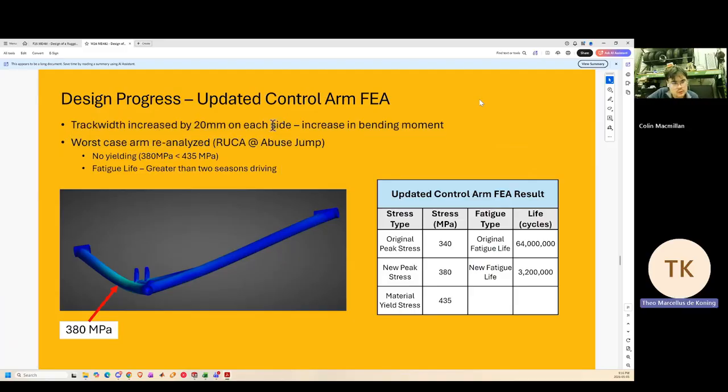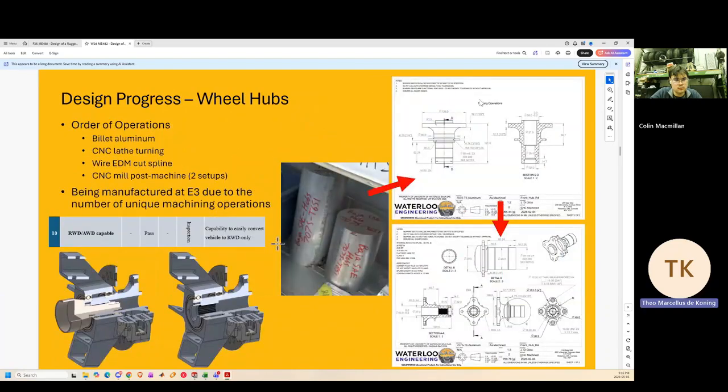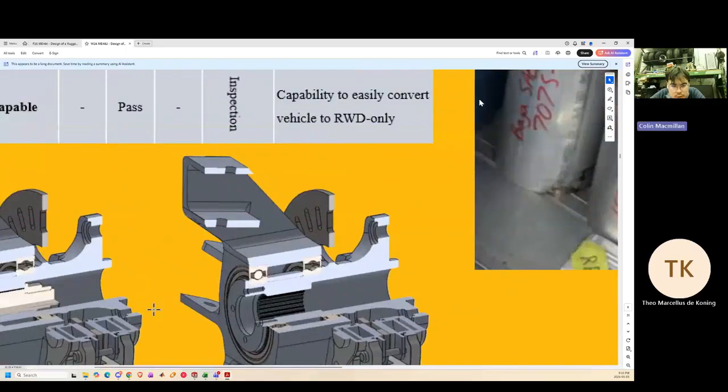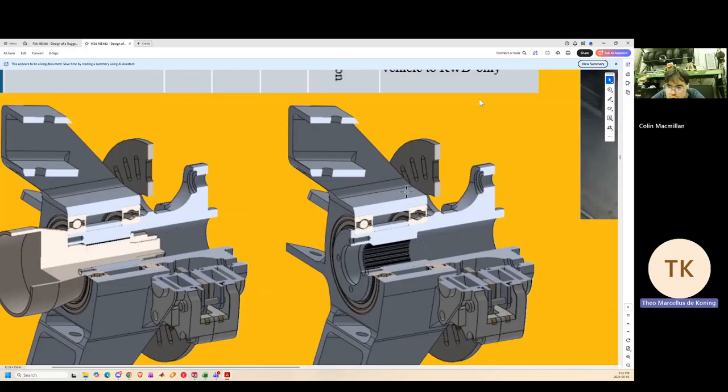And then we increased the track width by 20 millimeters to be able to use 2 single row ball bearings. In the past, we used a single giant double row. Versus now we have 2 single row bearings that are spaced out. And what is between the bearings? Just a spacer, yeah. Okay. So this makes it a lot more stable, with a lot less bearing load.